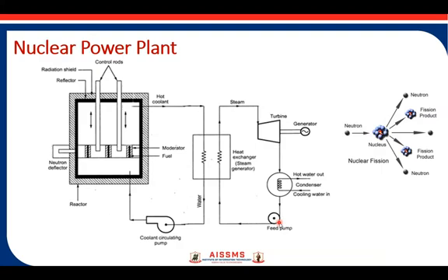Whereas investment cost is very high as compared to the others. The burnt fuel is highly radioactive. The danger of radioactivity is more. It cannot be operated efficiently at varying load. The maintenance cost is also high, and disposal of fission products is a big problem for nuclear power plants.